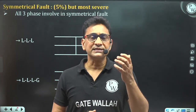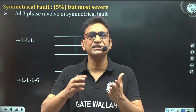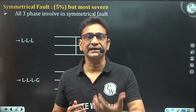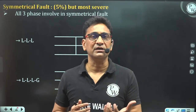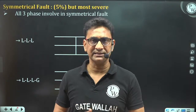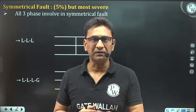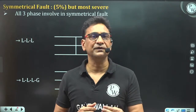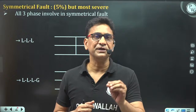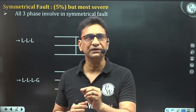So in the symmetrical fault, even if the magnitude of current has changed from its normal value, the system will remain in the symmetrical condition, or the balanced condition. That means the current at the time of fault in all three phases will be equal in magnitude, and there will be a phase difference of 120 degrees between the A phase, B phase and the C phase current.